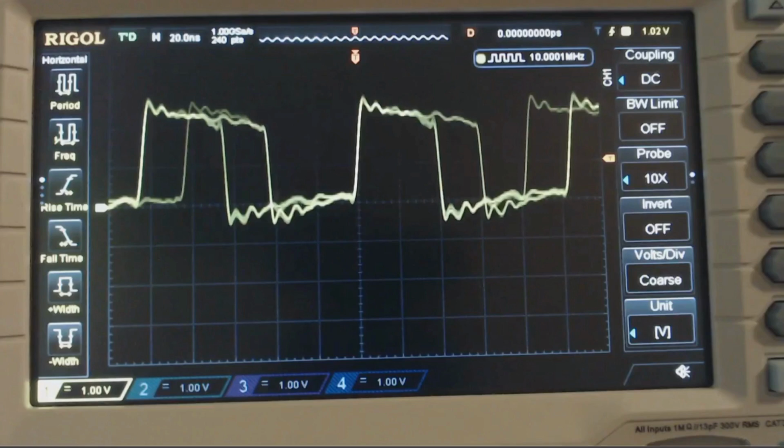This is the 10 MHz signal we just specified in u-center. I'm using the 50 ohm output signal, and I terminated the scope with a 50 ohm resistor to reduce ringing at least somewhat on the higher frequencies. That's why the signal is showing only just over 2 volts amplitude. While this output looks terrible and full of jitter, other frequencies were clean enough.